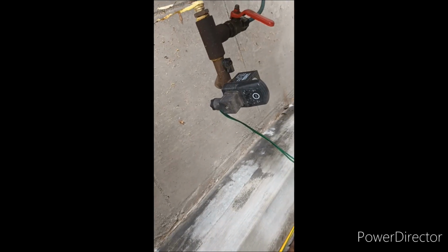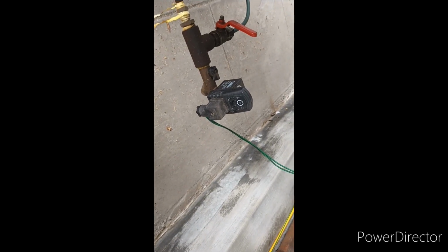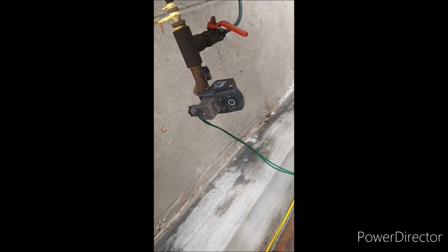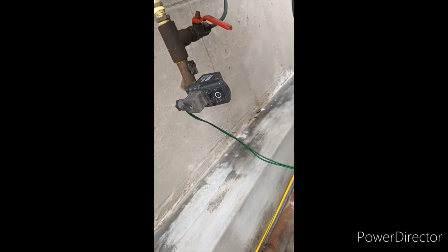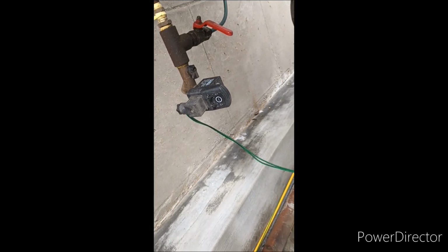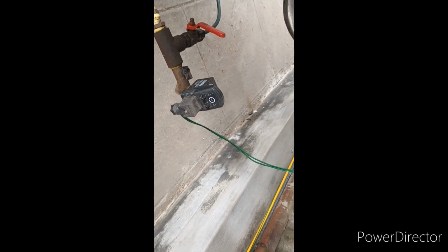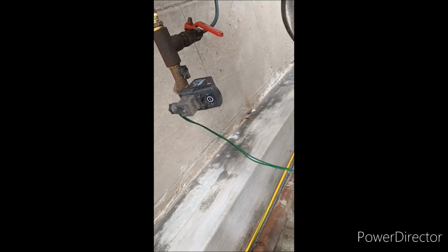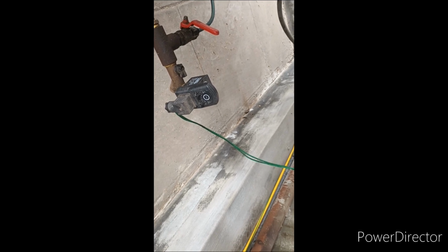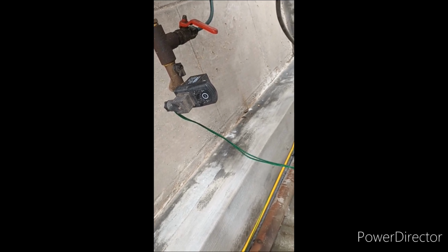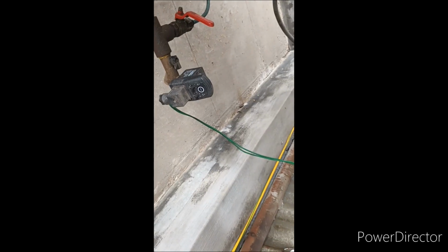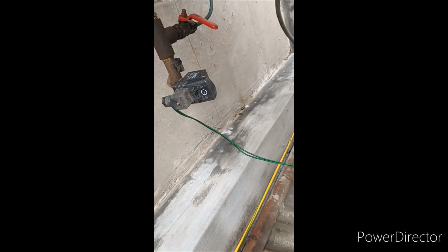In a normal auto drain solenoid valve with timer, you will lose some amount of air, because the solenoid valve comes with a timer attached. On time and off time can be set on the timer. The solenoid valve will remain on for the set time, and then will remain closed for the set time. For example, you can set the solenoid valve to remain on for 5 seconds.